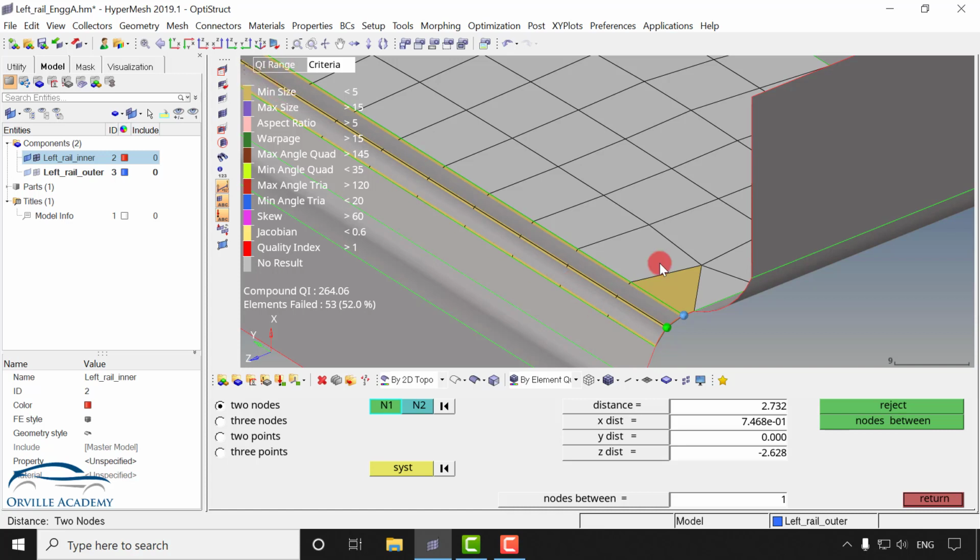In such cases, you can do two things. First, you will call the team leader and ask which one is important: whether it is important to place the 2 elements on the fillet or to follow the element quality. If he says that it is important to follow the element quality, then on the fillet we are going to put only one element.